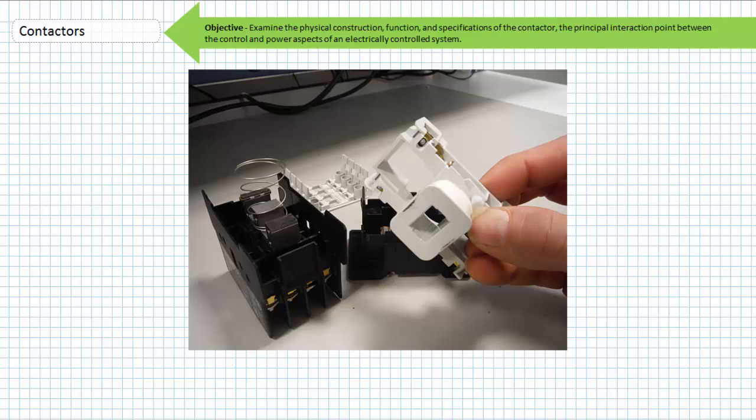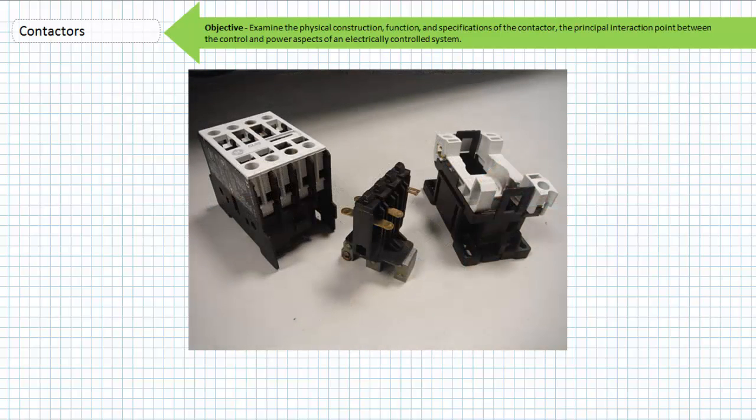Here's quite literally an exploded view of a contactor that had a bad day. In this case, I've fully removed the contact carrier still attached to the armature. Notice one of the contacts is totally missing, and note the visible scoring on the faceplate and the coil. This contactor went phase to phase and suffered the consequences. We'll discuss mechanical, electrical, and push-button interlocks that can prevent this from occurring in later lectures.